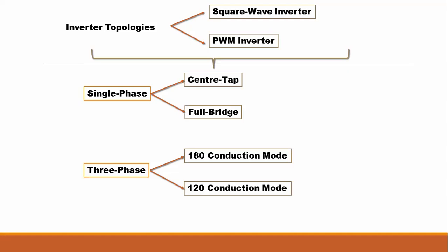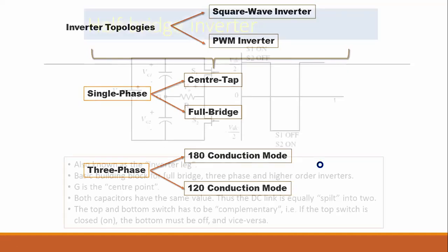In inverters, diodes and thyristors are used, and depending upon the load, if the load is resistive, then one type of conduction mode is required. But if the load changes to inductive, then the conduction duration of the thyristor changes. We will go through the effect of the load changing, and what type of strategy is required, later on.